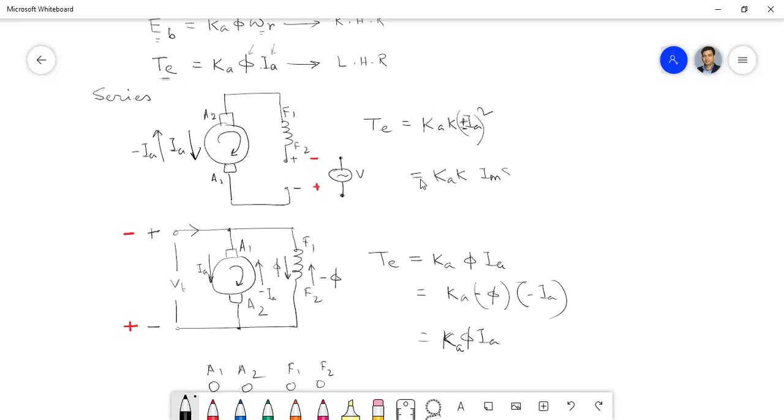Sir, speed will no longer be constant because pole induction strength is continuously decreasing and increasing. At what frequency? Suppose the frequency I have given is 50 hertz. Okay. So can you visualize this 50 hertz by your naked eyes? No, sir. Then how can we say that the motor speed will reduce then increase, reduce and increase? Is it possible? Due to the inertia, it will rotate.